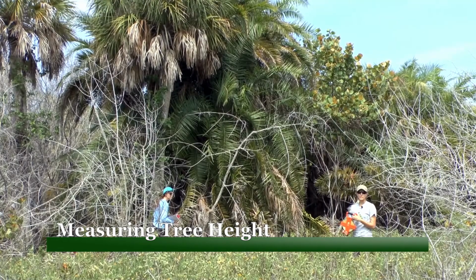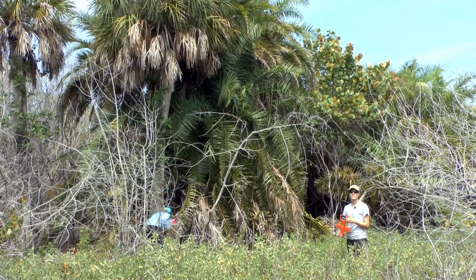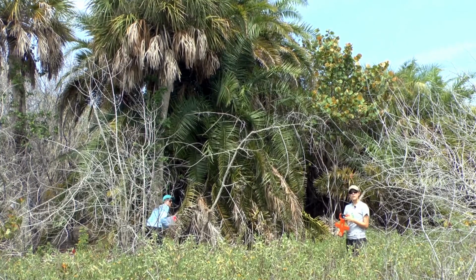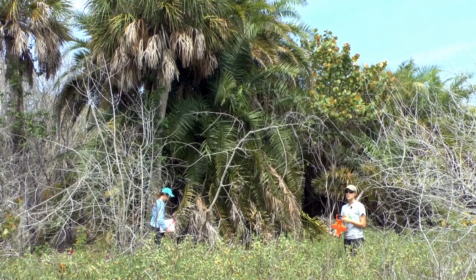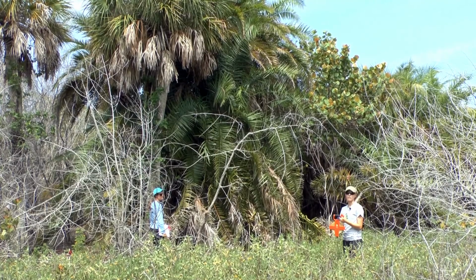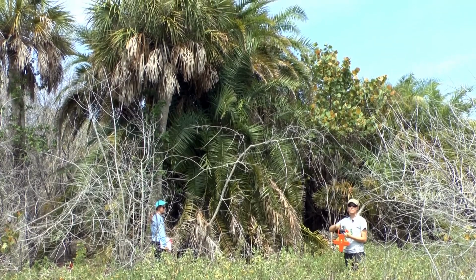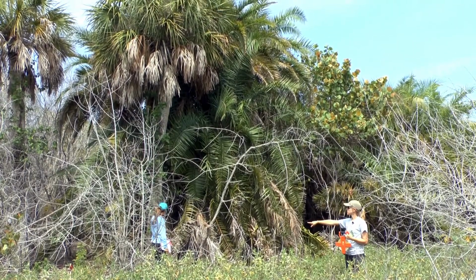Measuring tree height. For all of the trees that you measure for PCQ sampling, we're also going to record the tree height. So you can use a survey rod to record tree height. If you don't have a survey rod, we can determine it using a clinometer. So for that, we need to measure the distance from the person taking the measurement to the base of the tree.